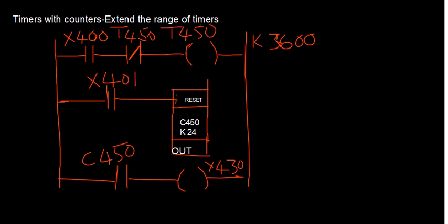Suppose you want the entire program to give you a 10-second delay, whereas your loop is giving you only 2 seconds delay. What you would do is repeat it 5 times from an external count. You take an external count which is initialized to 5, then you get a 2-second delay, then make it 4, then again you get a 2-second delay. I think you can quickly recall these things since you have already studied either microprocessor or microcontroller. This is the logic that is generally used, and a similar technique here is used to extend the range of the timers.